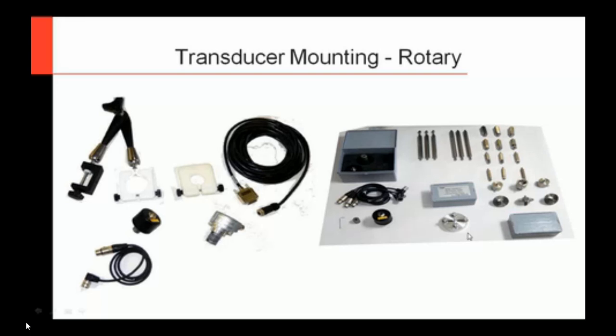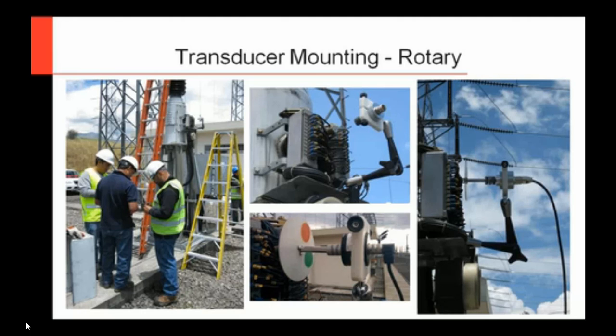And you'll see there's a variety of different brackets and bolts to hook onto different styles of circuit breakers. But here's an example. Generally, what I've seen is most live tank circuit breakers use a rotary type transducer. There's occasionally, like anything, ones where you use a linear type, but most people prefer a rotary type on a live tank. So they came up here, and this is your open-close indicator, but we can hook directly to there, and it rotates along with that circuit breaker so many degrees, and however many degrees equates to a certain amount of millimeters in travel length.